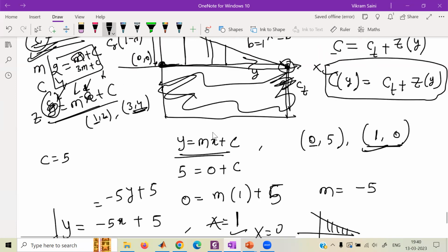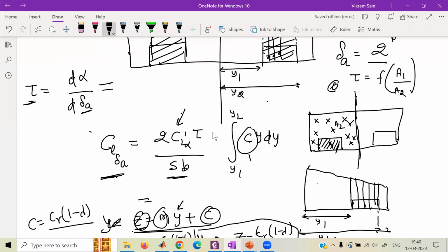Yeah, and we have derived this in one. I already discussed that you can take a CL alpha for an airfoil, then you convert it into a finite wing, taking the aspect ratio, the geometry that we are given, and then find out the finite wing CL alpha. How do you find tau? You can find out the aileron area and the overall wing area. Divide the two, you have a ratio. That ratio dictates the tau, something like this, and I had shown you. From that you can find out tau.